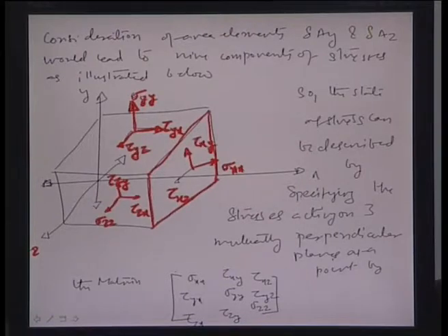Okay. So, here if you put all these stresses together in a matrix form, you can define a matrix which is also known as a stress matrix, where you have the diagonal elements which are principal stresses in the x, y and z direction respectively: sigma xx, sigma yy and sigma zz. The non-diagonal elements represent the different shear stresses, as has been illustrated before, with a certain notation. Okay. So, this is tau zy, this is tau yz, and so on and so forth.